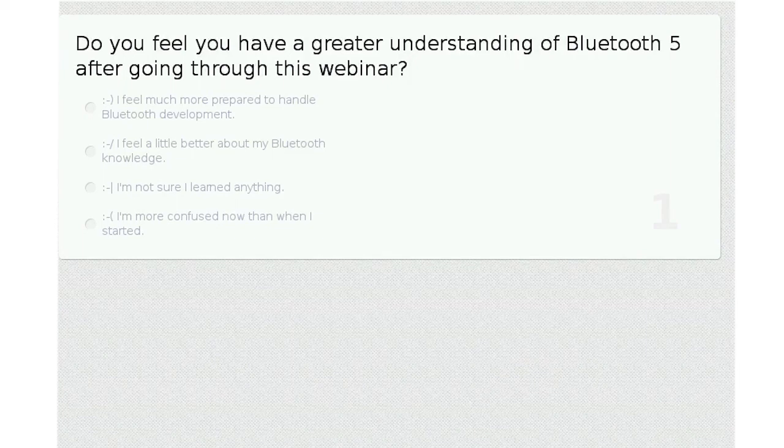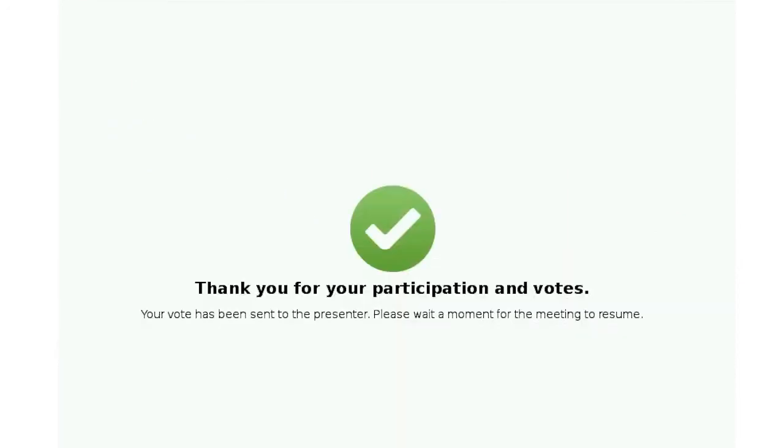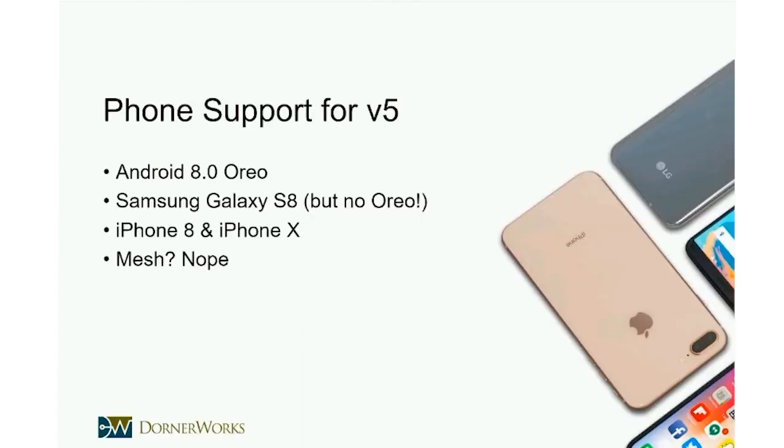Grant has another question about frequency hopping. He's wondering if it's automatic, or does it change on a per packet basis between hops? It's agreed upon at connection time. When you first establish the connection, your central and peripheral devices negotiate the pattern you're going to use. With the exception of some of the adaptive features, it's not on a per packet basis where you say, next packet send it on this, next packet send it on this.